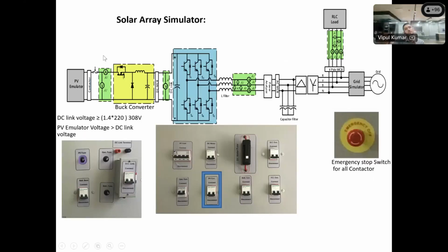When that switch opens, we measure how much voltage we are getting. If I am getting 100 volts, that is the VOC. Then we take power such that the voltage is 80% of the VOC. In that way we operate in constant voltage, and for constant current, we put an electronic switch between plus and minus after the sensor.